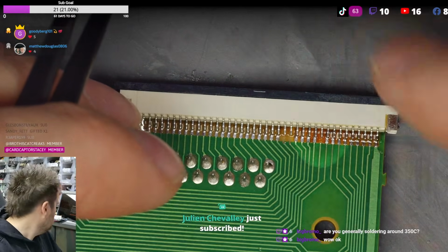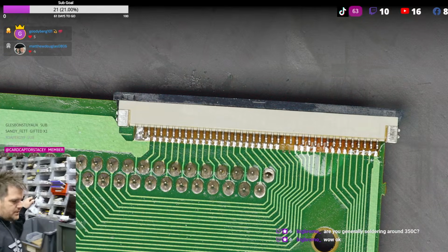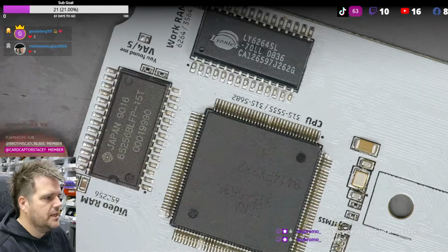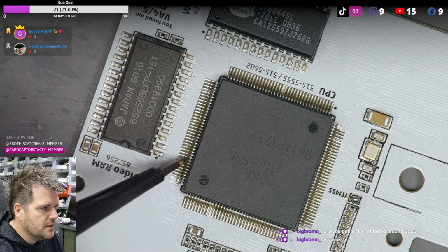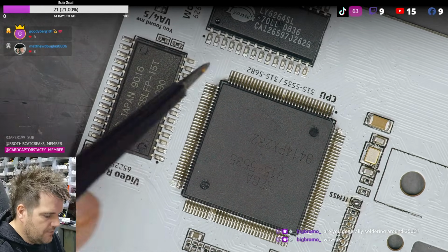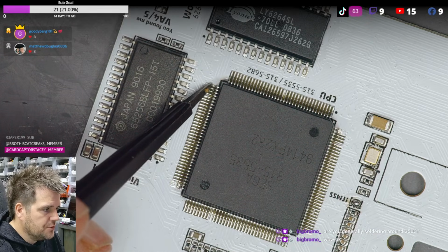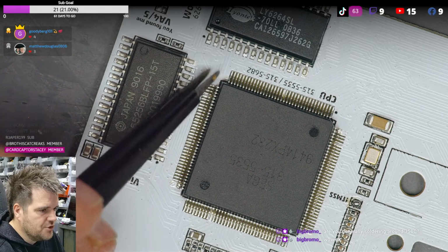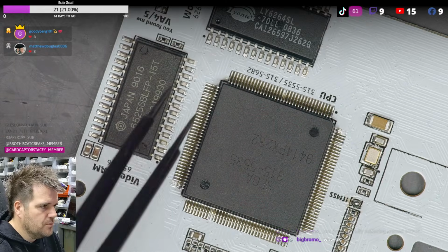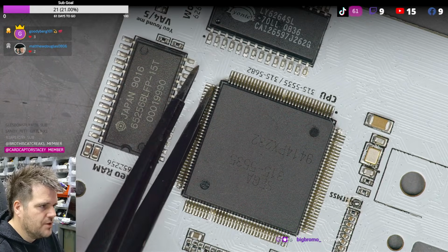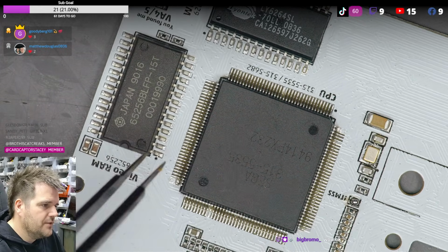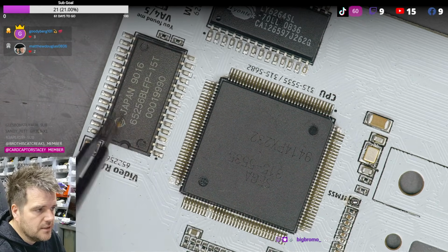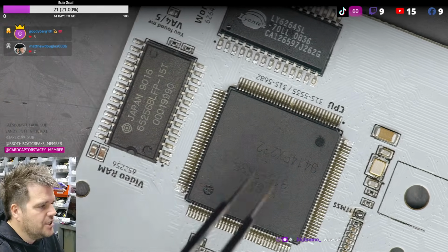If you get, though, say, for example, the Game Gear RePCB or the ASIC, these pins, the finer pitch, and if you apply much pressure, like not much pressure at all with your iron, you'll bend these pins as you drag solder. So these you want to almost rest your tip on without any pressure and drag with no force on the tip. Even worse than that, if you go to Mega CDs, the Mega CD Engine IC, which I can probably show you.